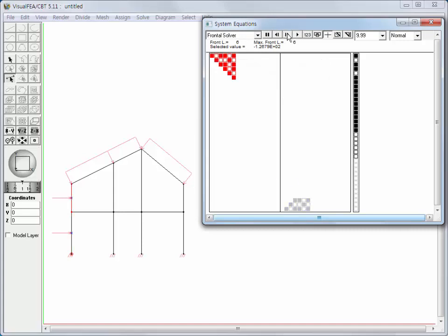The next element is assembled filling the unoccupied memory space, including the space vacated by the elimination. At this stage, no additional nodes with complete assembly. So, go for the third element without any elimination. The third element is assembled. There appears an additional node, for which the assembly is completed. The completed node is marked by small circle, again. The associated entries are eliminated. The procedure of assembly and elimination is repeated for each of the elements in the order of element number.